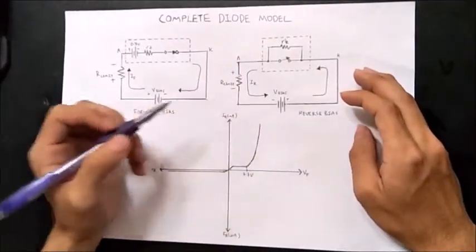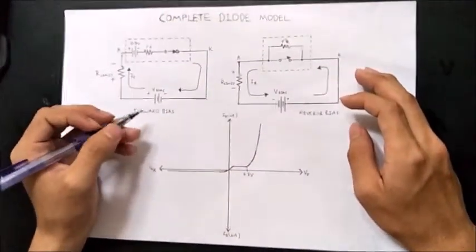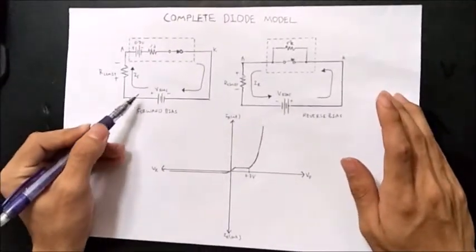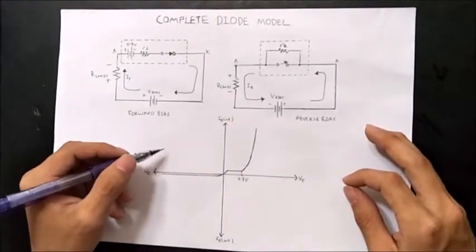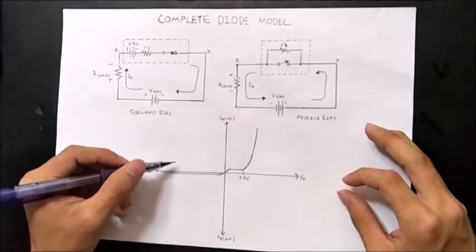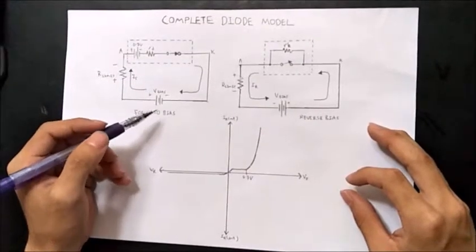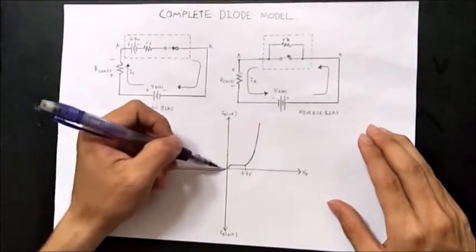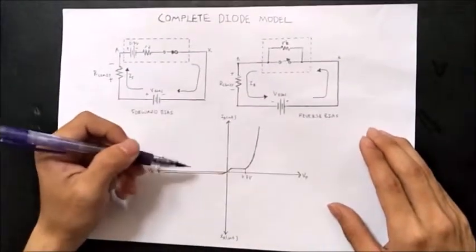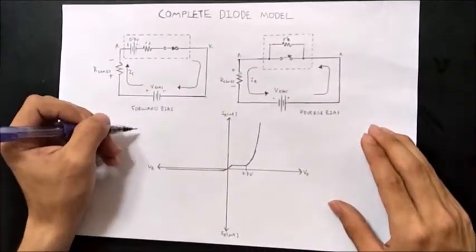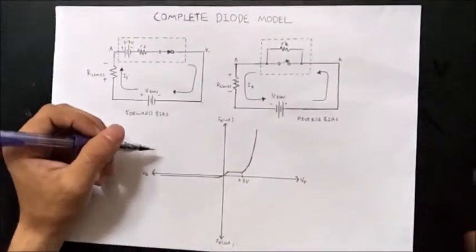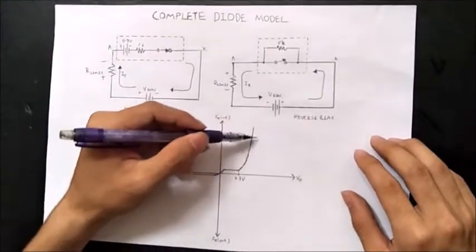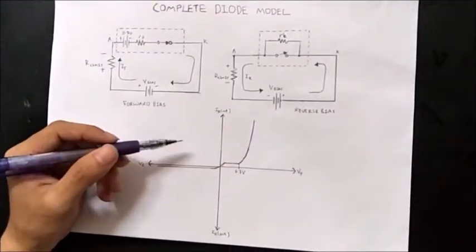The diode is assumed to have a voltage across it when forward biased, since the barrier potential and dynamic resistance are included. This voltage consists of the barrier potential voltage and the small voltage drop across the dynamic resistance. The curve in the graph slopes because of the voltage drop due to the dynamic resistance as current increases. Reverse current is indicated by the portion of the curve to the left of the origin of the graph.